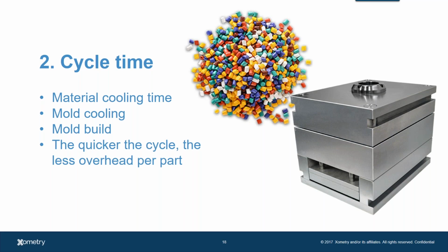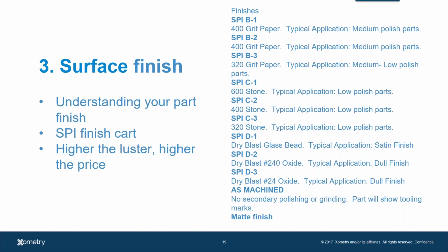This is also something that comes in when you talk about what production level you want, right, Travis? Sure. So if I have an order quantity, say I want 50,000 a year, then I should be expecting 1,000 parts a week once I'm into production. Sure. So when you start saying I want more than X, you have to think about different ways of managing, whether it's family molds or other ways of designing this. But it is really important not only for your initial order, but to know what the future of this order is, because it does help us make a better decision on what tool you will choose.